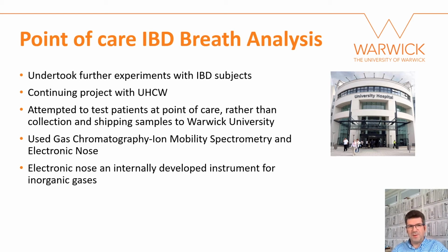So what we decided to do is look at some further experiments with IBD. We sent all the equipment to UHCW and ran the experiments there instead of here at Warwick. In this case, we sent two instruments. We used a gas chromatograph ion mobility spectrometer, and we sent one of our in-house electronic noses. This electronic nose is slightly different to most common ones because it's designed for inorganic gases, so it's detecting things like CO, NO2, etc.